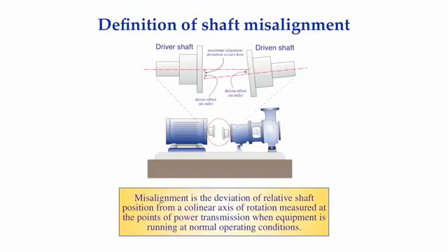So I began to see if there is something common with all flexible couplings, and after a lot of study, I realized that there is one common feature that every flexible coupling needs to have, and that's this. For a flexible coupling to be able to accept both a parallel and/or an angular misalignment condition, it must have two flexing points in the design. So let's take a moment to examine what is meant by the flexing points in a coupling.